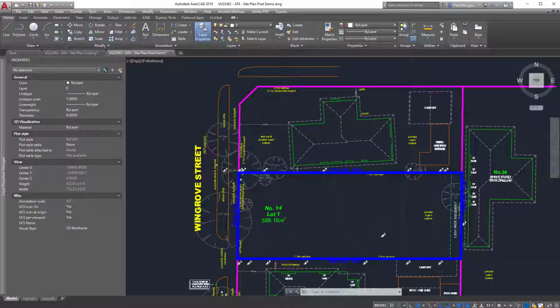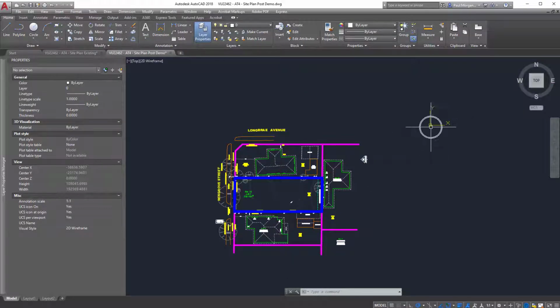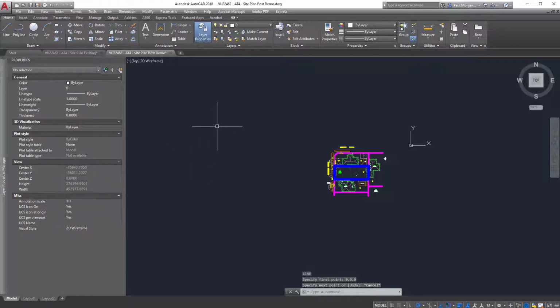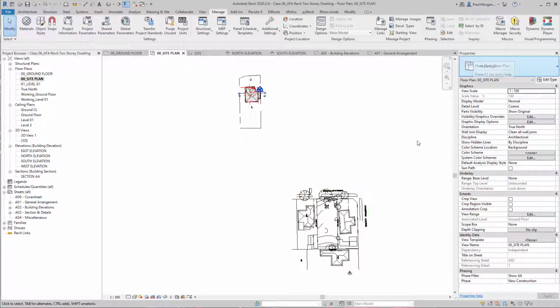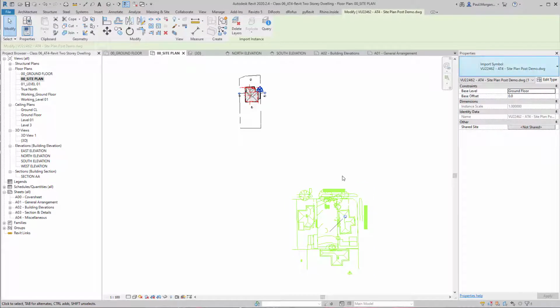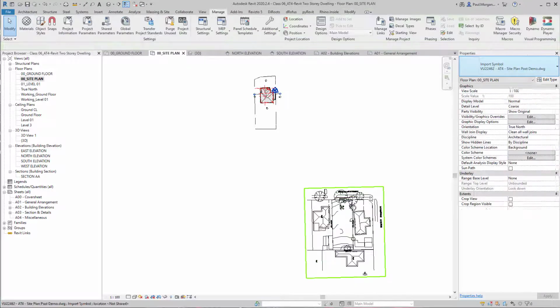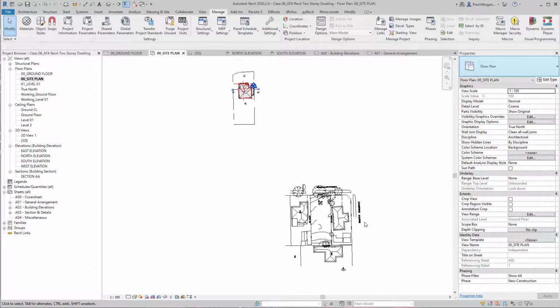So if I go to my Revit file, you can see the 0 point is over here. So if I go like line 0, 0, 0, it's only from here. If this survey file was actually geolocated, it would be like 50 kilometers away from this point in the middle of no man's land. And then the CAD drawing would actually be geolocated, and we wouldn't have to do all this sort of rotating and moving and aligning and all the rest of it. So it is a bit of a side effect of that issue. However, it's one that you may experience in your time. So it's actually a good thing that it's happened, because I'll show you what I would do in this scenario.